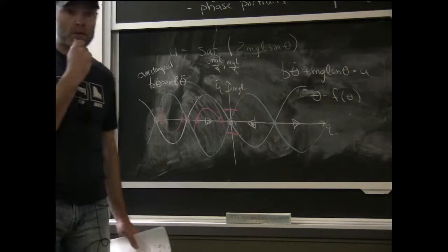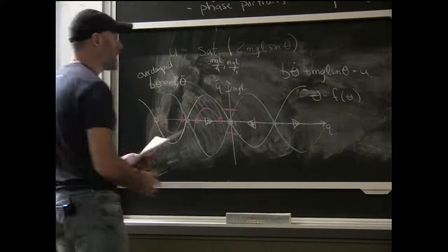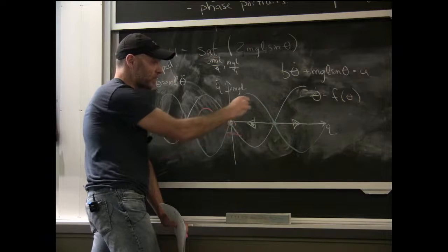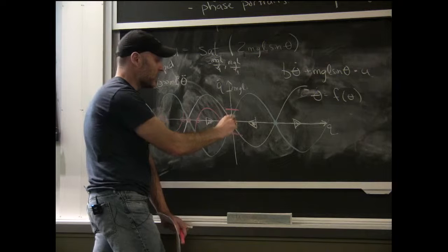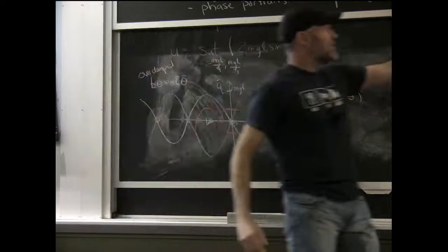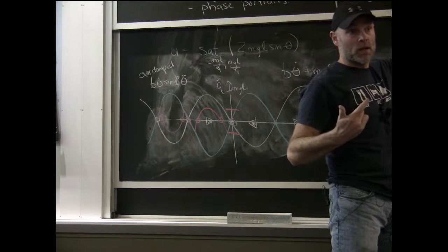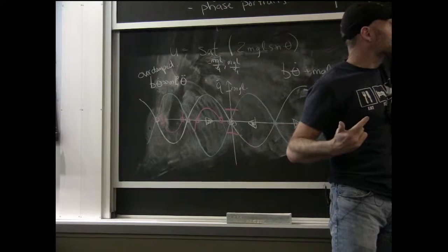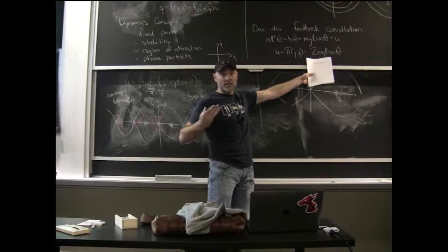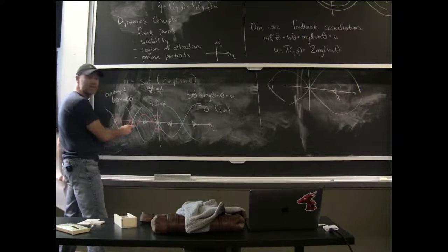So blue would be the unsaturated control. Yes. And then red. Red is what? Yes, good. So red is going to act like the blue in some regime, right? Where the demand on torque is small, then you get what you asked for. When sine theta 2 mgl is less than mgl over 4, then you get what you ask for. When does that happen? That happens here, and it happens here.